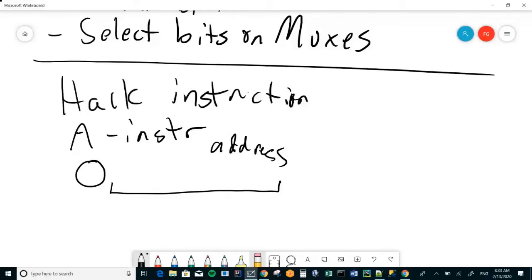Any question? Yeah, so then obviously bits 0 through 14 are going to be trying to go into the A register, but there are other things that can go in there. So there's going to be a multiplexer, right? Because we can have an ALU output also going to the A register. So it's important then to make sure that we're clear on the fact that there are these multiple possible sources for its value.